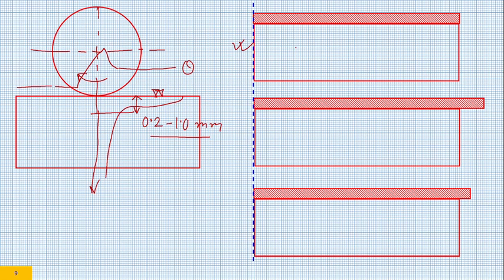So this is my workpiece. Now, what I have done is I have segmented the workpiece into 2 pieces. The thickness of this top layer is more or less equivalent to this. During grinding, this top layer goes to a high temperature. As it goes to high temperature, it tries to expand from this point to this point. How much would that expansion be? That expansion would be alpha into theta into LW.